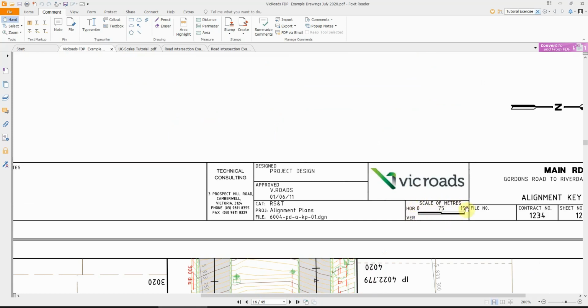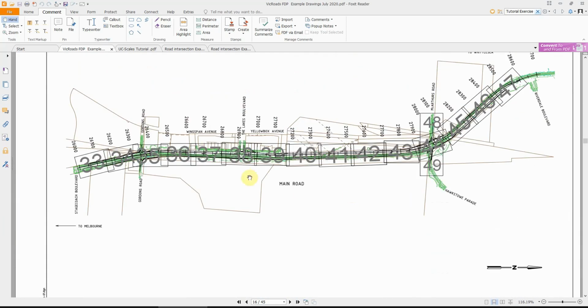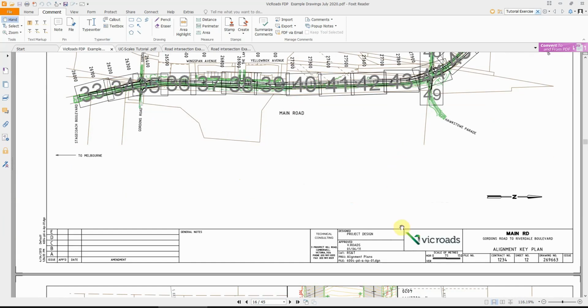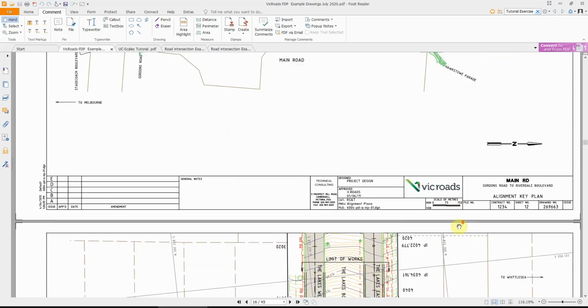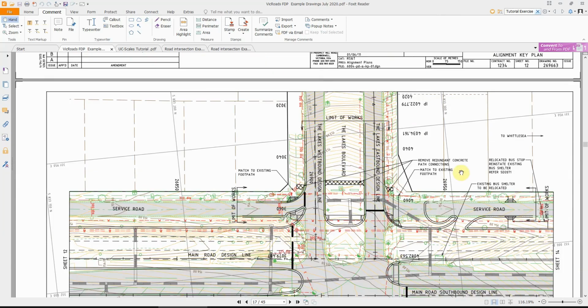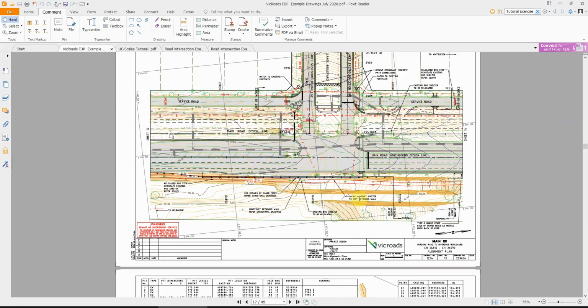That shows that if you measure from here to there, that should be 150 meters. That helps you take any measurement on this plan and compare it to that, and you'll be able to get the length. That measurement here is 150 meters, whereas on this plan the exact same measurement is only 10 meters. So that's why scales are very important for us to understand and to be able to work with freely and comfortably.